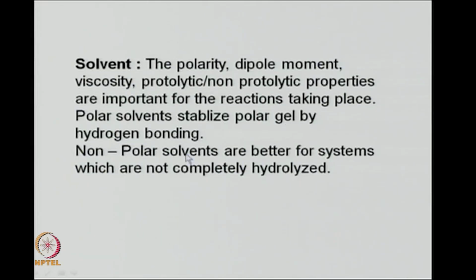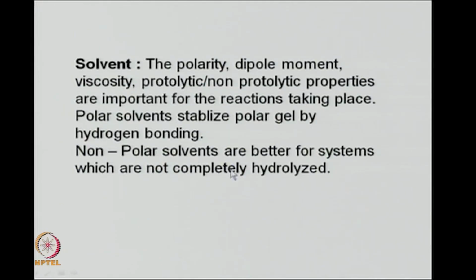Polar solvents will stabilize the gel by hydrogen bonding, that is very important. When the gel is formed from the sol, because the solvent is still present in the gel, the polar solvents will stabilize the gel through hydrogen bonding, whereas non-polar solvents are better for systems which are not completely hydrolyzed. So, depending on your kind of system, the solvent has to be chosen to give you the right kind of mechanical strength for the gel.